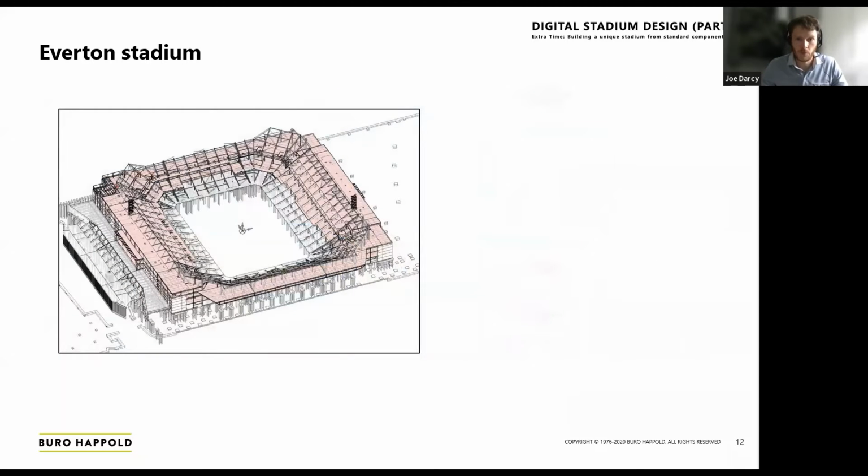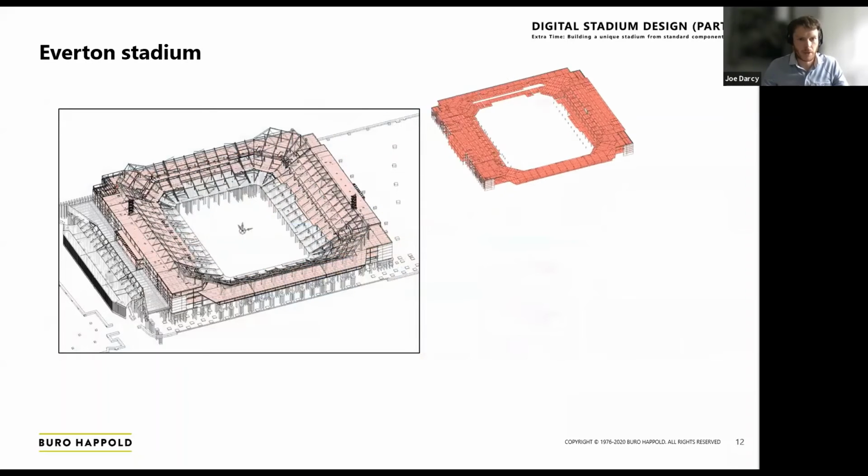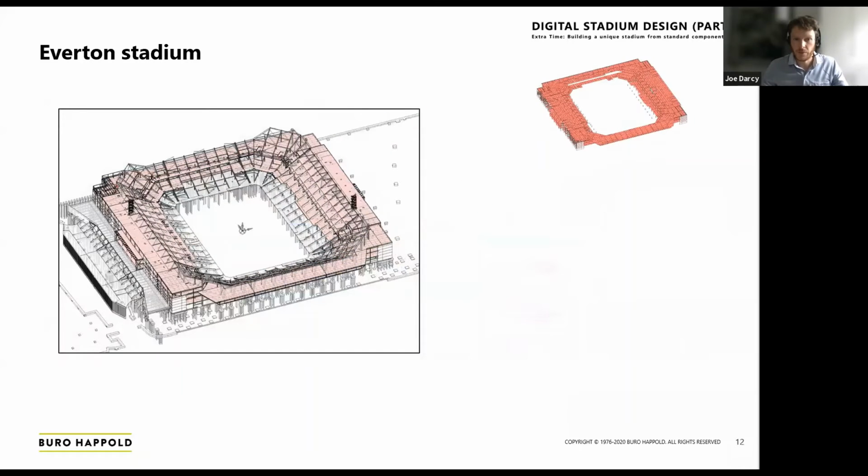Just to give you a brief description, a bit more detail on the DFMA items implemented on Everton. The lattice planks are a precast biscuit with a girder system, completed on site with an in situ topping and reinforcement.